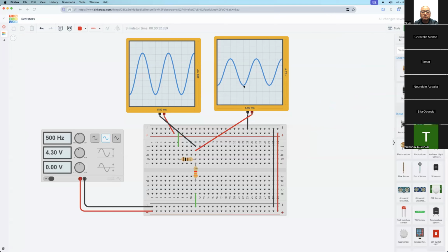So now the peak to peak value for this 3.3 kilo ohm resistor is 4 volts: 1, 2, 3, 4, 4 divisions, times 1 volt per division, so totally 4 volts peak to peak. Okay, this is great. Then we need to measure, now back on the left oscilloscope, the voltage across the 100 ohm resistor.